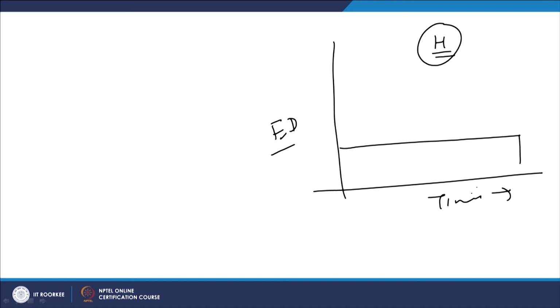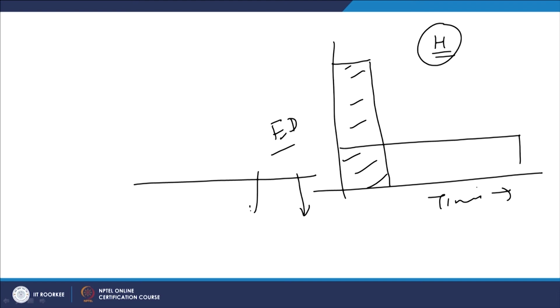When the energy density is high, it is required to supply the energy for a shorter period for the same amount of heat. But we know that when energy is transferred for a longer period, a lot of heat or energy will be dissipated to the underlying low temperature base metal, and that is why the actual amount of heat required for melting using the low energy density process is higher as compared to the high energy density process, because the amount of heat transferred to the underlying base metal is significantly lower in the case of the high energy density process.